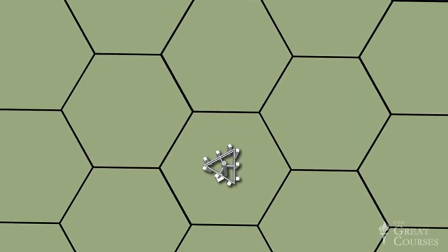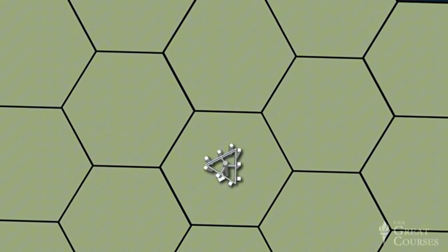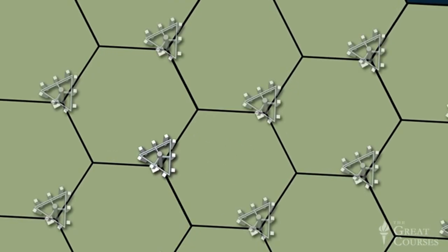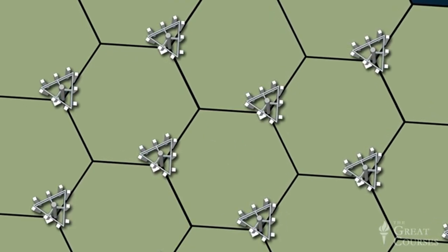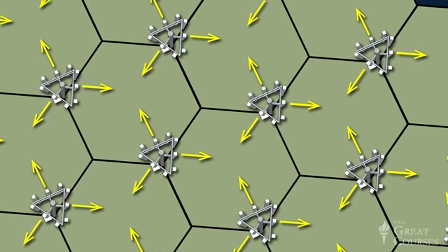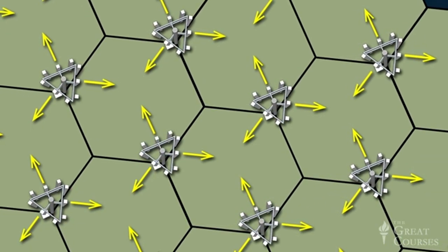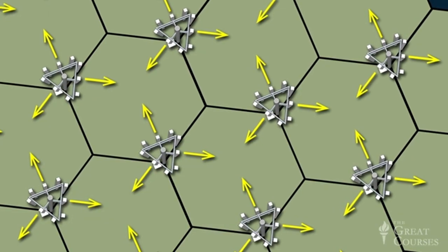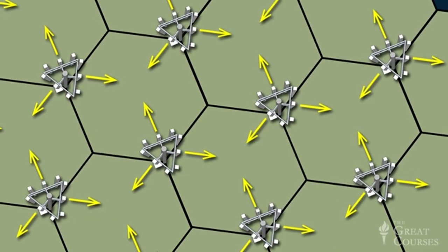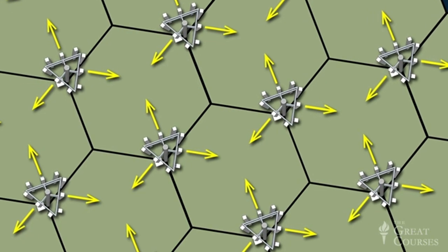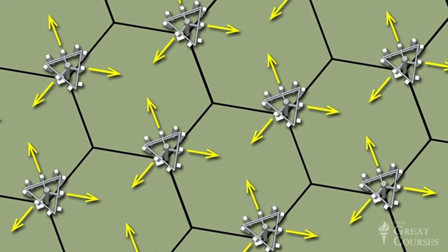One common technique for achieving better coverage has been to place the antennas not at the center of each cell, but rather at 3 of the corners, like this. With this configuration, directional antennas are now used to limit each tower's coverage more effectively to the assigned cell. Note also that in this configuration, each cell is served by 3 different towers, providing more uniform coverage, and each tower covers 3 different cells.